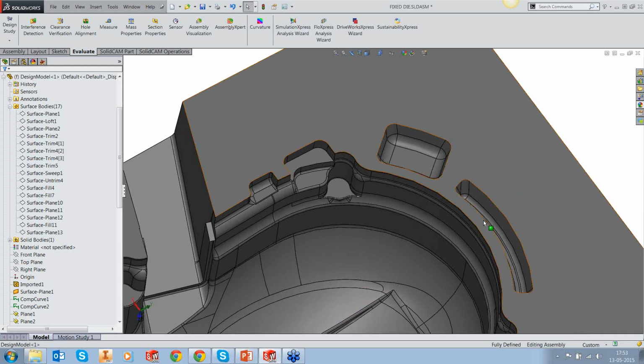Even if there's a cutter capable of getting inside this, it will only waste my time, because it's not going to finish it in any way. So why do it in my regular machining? We can do it later with a small tool straight away, rough it and finish it. So this particular pocket and this particular pocket need to be closed off.